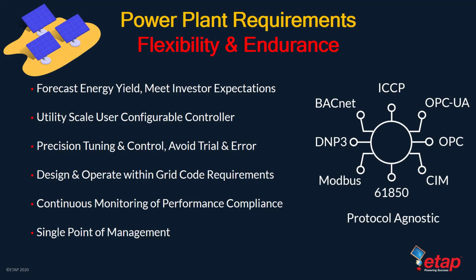An important step in assessing project feasibility and attracting financing is to calculate the electrical energy expected from the PV power plant. The energy yield prediction provides the basis for calculating project revenue. The aim is to predict the average annual energy output for the lifetime of the proposed power plant, which is typically 25 to 30 years.